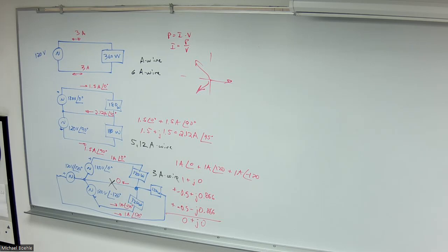Better than a single-phase motor where I try to create that rotating magnetic field using a capacitor to create a phase shift between the 2 phases. So massive industrial motors that have to draw lots of power are going to be 3-phase motors because they just work a whole lot better.